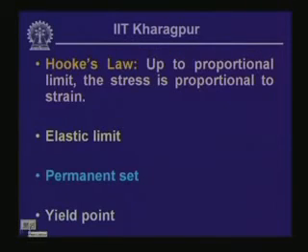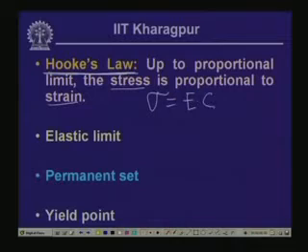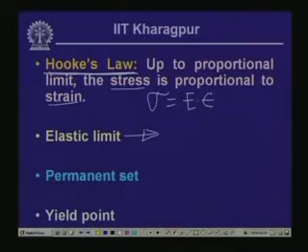So we have seen Hooke's law, which says that up to the proportionality limit, the stress is proportional to the strain, and thereby we get sigma is equal to E times epsilon. We have seen the elastic limit, as I said: if the bar is loaded and allowed to extend, and the bar is within the elastic limit, if we release the load, the bar is expected to come back to its original state.